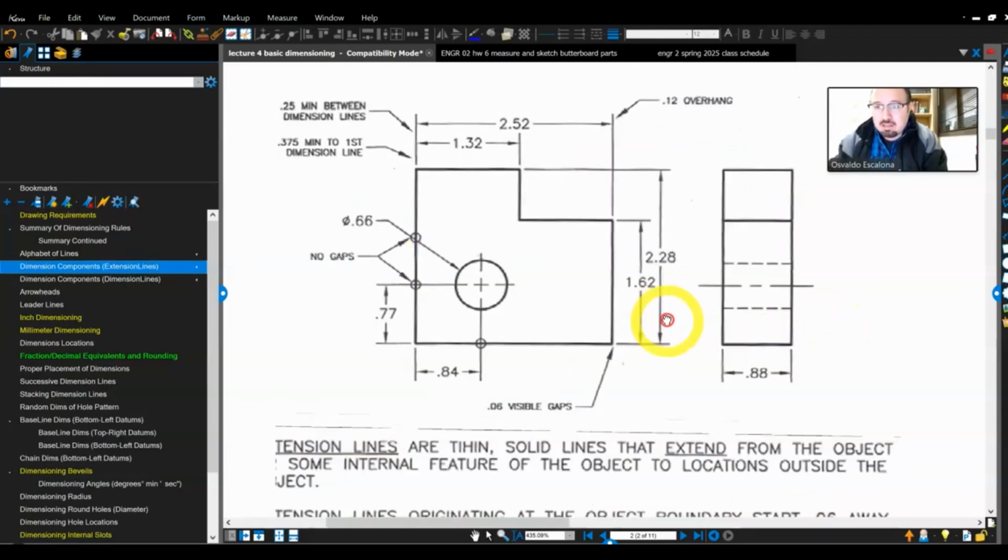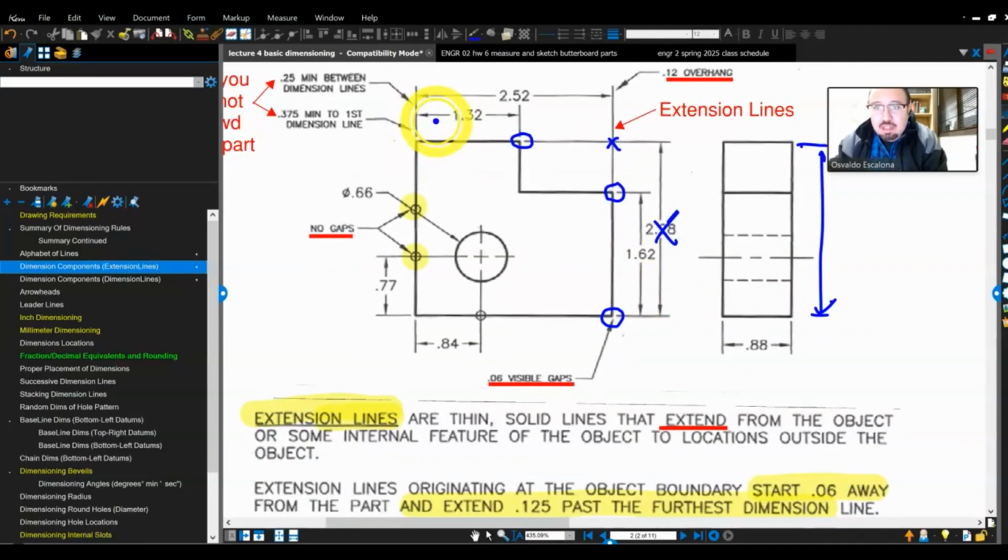The spacing. You will notice you have a dimension line. Again, the dimension line is this one, right? You have dimension arrows. There should be a gap between the part, and I previously told you it's about 3 inches on each. Consecutively after that, you will have a dimension spacing of 1/4 of an inch minimum. In other words, there's not really a standard that says you have to have a quarter. You can make it bigger as long as things are uniform.